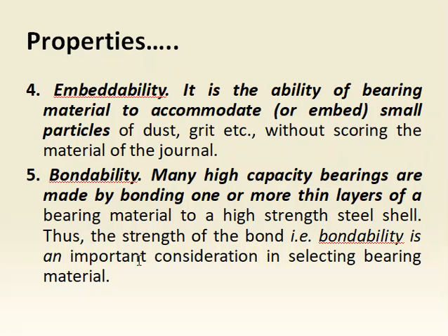Next one, bondability. Many high capacity bearings are made by bonding thin layers of the bearing material to a high strength steel shell. So the steel shell must have high strength and a good bond with the surrounding material. Bondability is an important consideration in selecting a suitable bearing.